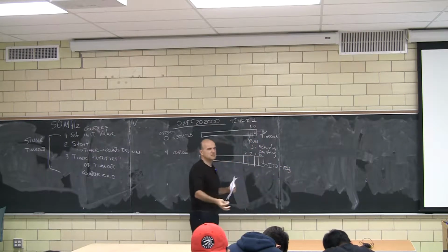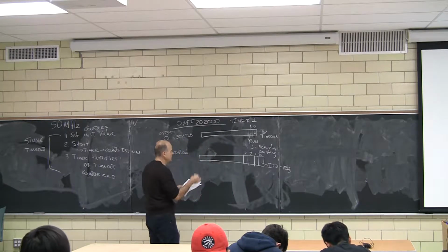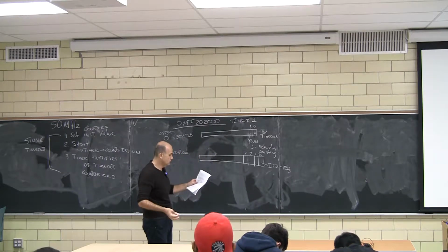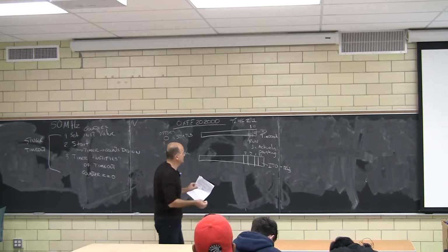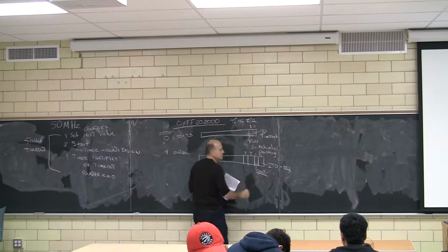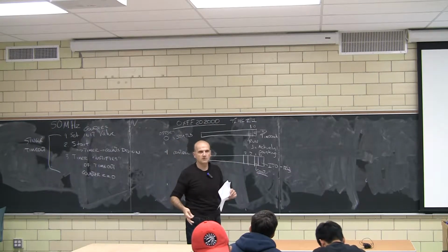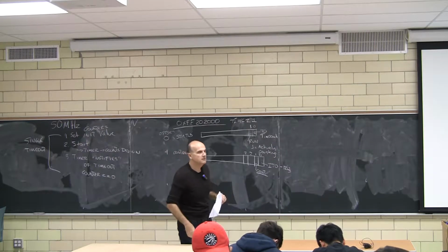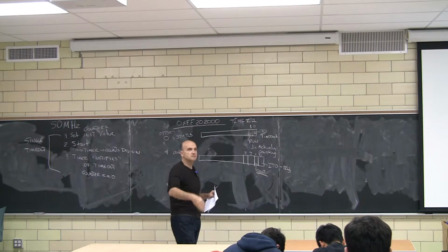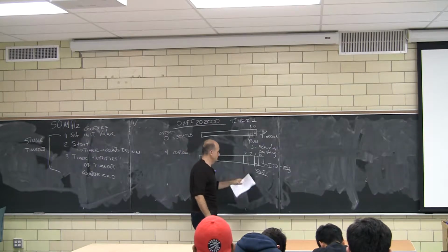Again, these are design decisions that the designer of the system has made. Now, 0 means don't raise interrupts. We're supposed to talk to you through polling. Now, this one: 0 means single run, count down to 0 and stop. 1 means once you do that, reset yourself and count down again. This stands for continuous mode.